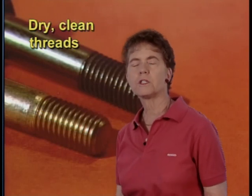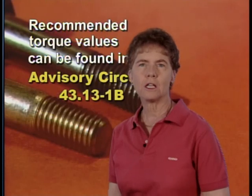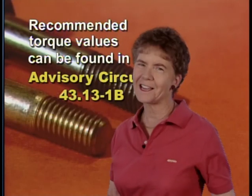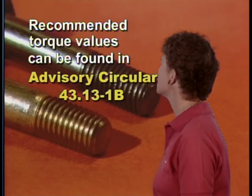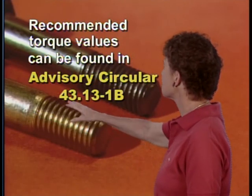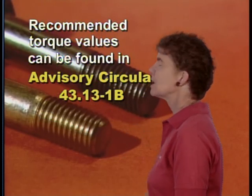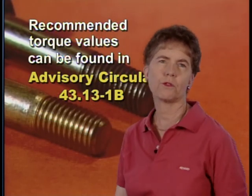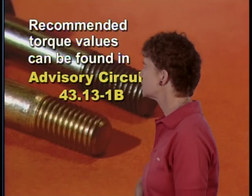Now, if the specific torque value for nuts is not given, the recommended torque values can be found, guess where? That same advisory circular we were just talking about, Advisory Circular 43.13-1B. So if they do not give you the recommended torque values, you can find them in this advisory circular.